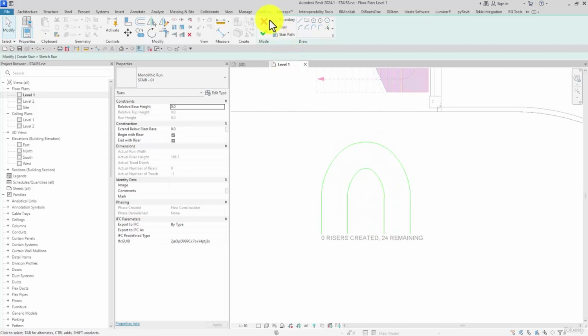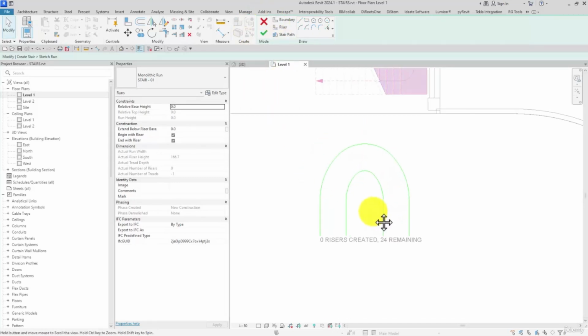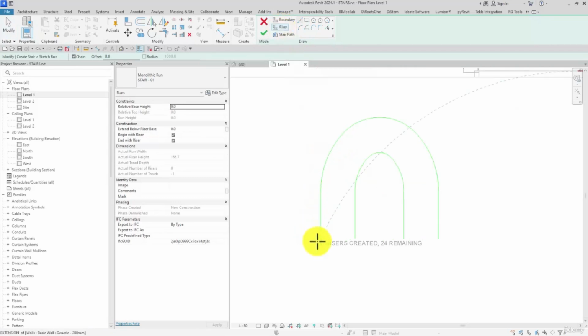Watch this. These are the boundaries or the supports of the stairs, which we cannot draw using the components. So firstly we draw the supports, or we draw the boundaries. We don't need to close these two curves. After drawing the supports, we pick Riser, and then we click. Watch this, and then pick Line. I specify 300s for the offset of the riser. Then we click on them for 5, 6, and we can add 18 more.